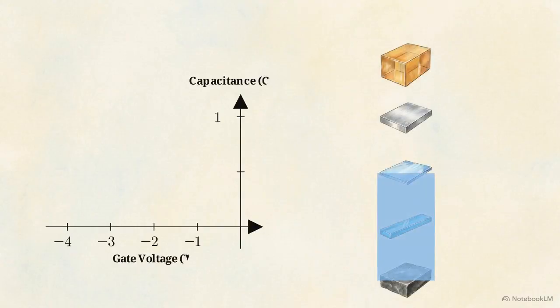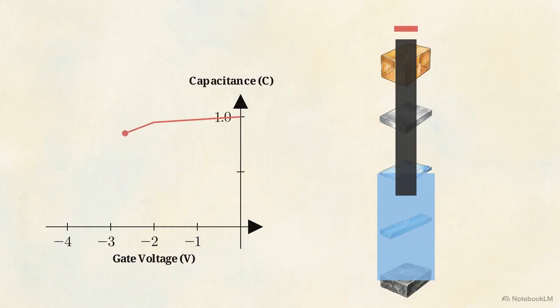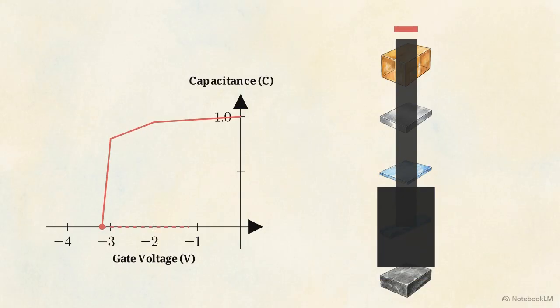If we apply a high negative bias to the gate, the electrons are pulled out of the space charge region. The depletion width expands infinitely large until the 2DEG channel is completely choked off. The point at which these capacitance curves drop to zero exactly matches this physical pinch-off, confirming that the thickness of the surface layer directly dictates the availability of charge deep within the device.